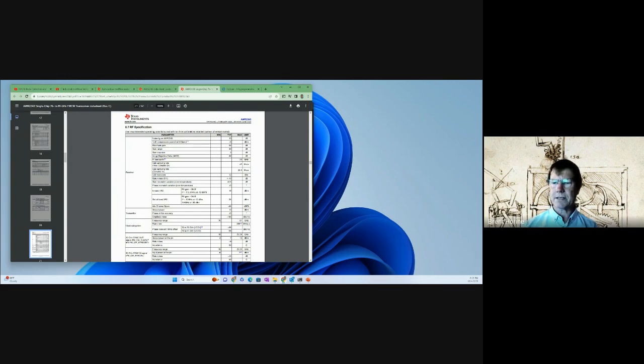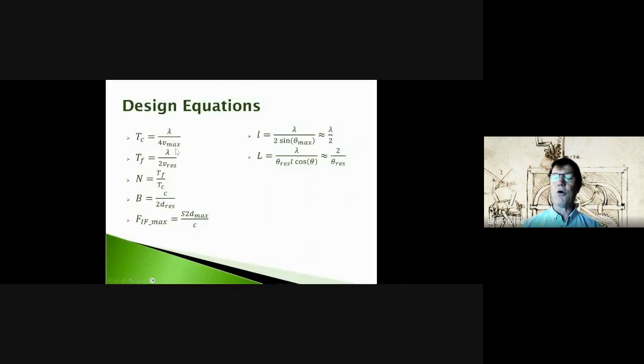There basically needs to be some overlap of the chirps when it comes back, right? So the receive chirp has to overlap that transmit chirp, and also I think in this case we're relating that TC to this maximum velocity, which goes back to that phase ambiguity that we might have when we're doing that Doppler FFT, right?